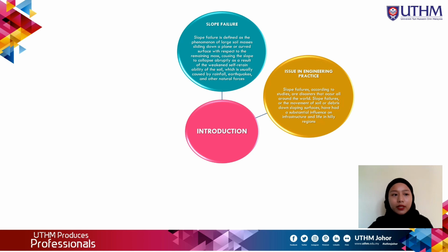Issue in engineering practice. In recent years, due to a lack of suitable flatland and other factors such as magnificent scenery, fresh air, exclusivity, and so on, the development of residential buildings on hillsides has increased dramatically. Gui and Tan 2006 found that 60% of failed man-made slopes were attributable to design issues alone, based on 49 cases analyzed. This shortcoming in design is usually due to a lack of knowledge and awareness of subsurface conditions and geotechnical problems.